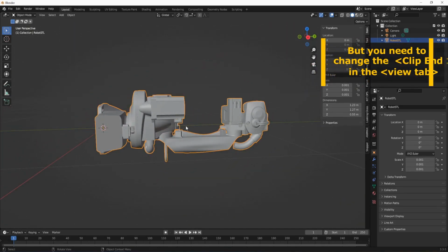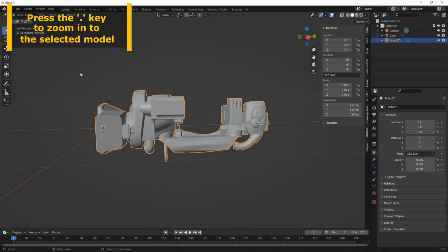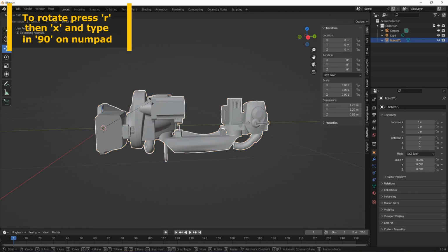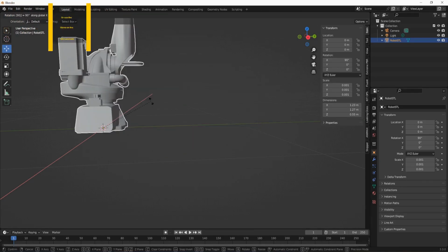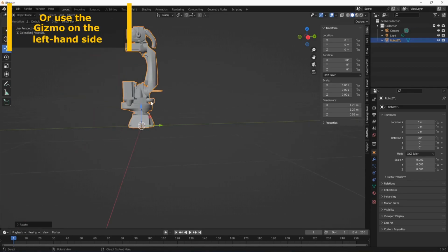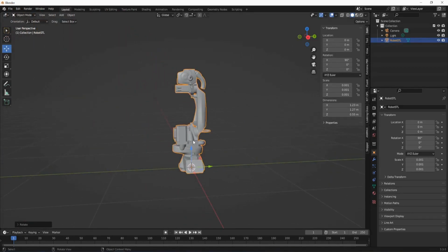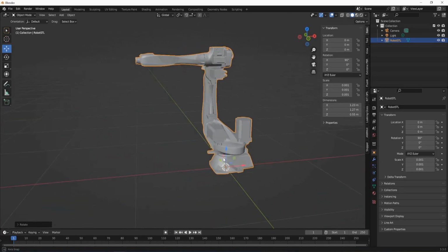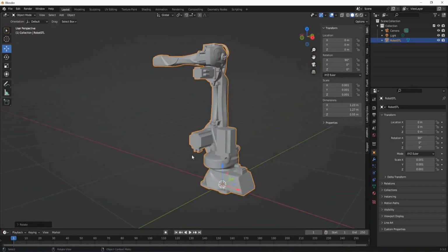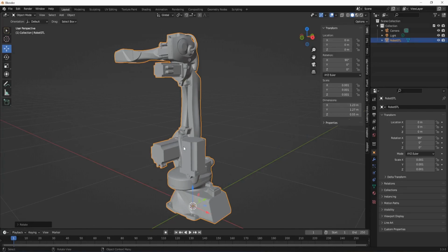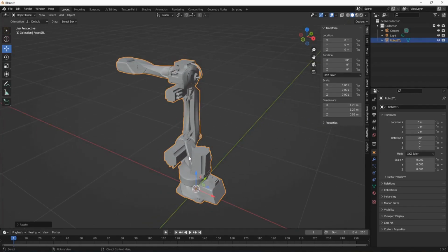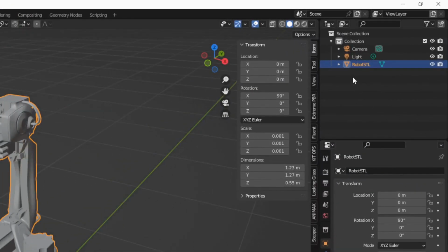And we see this is oriented over 90 degrees incorrectly for us because the Y is up in FreeCad and the Z is up in our program. So we can rotate over the X in 90 degrees. And we have the model imported. And as you can see, we have it available. At the first glance, it looks very similar to the step file, but there is a huge difference. So if we look in the hierarchy, we see that there are no different parts available.